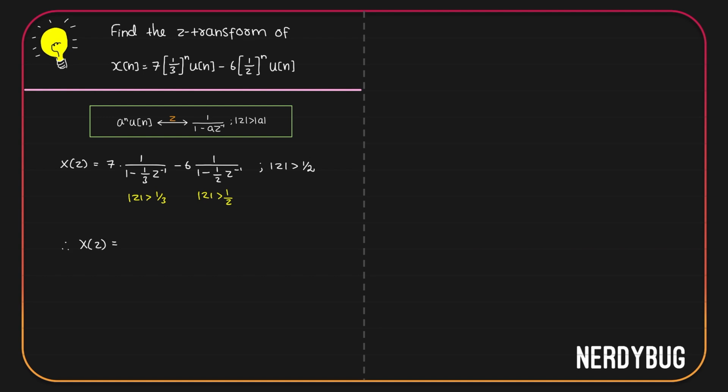So x of z is 7 divided by 1 minus 1 by 3 z inverse minus 6 divided by 1 minus 1 by 2 z inverse, where magnitude of z should be greater than 1 by 2. If we add both the terms, we get x of z is equal to 1 minus 3 by 2 z inverse divided by 1 minus 1 by 3 z inverse multiplied by 1 minus 1 by 2 z inverse.